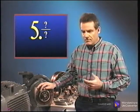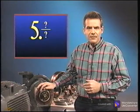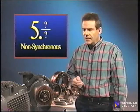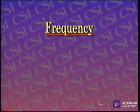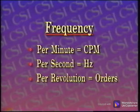This is the key to differentiating between bearing faults and other faults, such as vane pass, which would show up exactly 5 times for an impeller with 5 vanes. This fractional energy is called non-synchronous energy. That is, it is not a whole number multiple of the shaft turning speed, like 1.0, 2.0, or 3.0 orders. An order is a way of expressing frequency. Actually, there are 3 ways to express frequency: how often something occurs per minute or CPM, per second or hertz, per shaft revolution or orders.